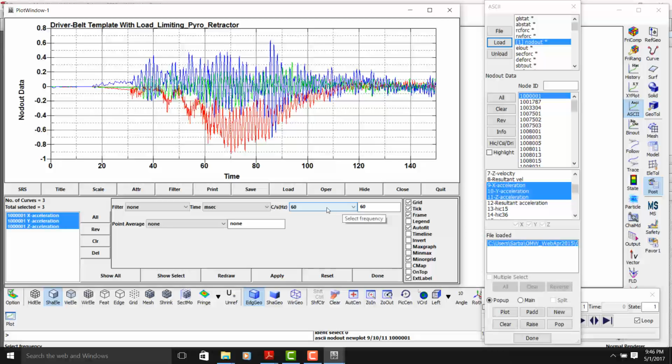So what is the relationship between SAE, which is CFC, and BW? Just remember one thing. If you take the frequency of BW and multiply it by 0.6, then you will get the SAE frequency. And the filters should be more or less the same, but the numbers are different.